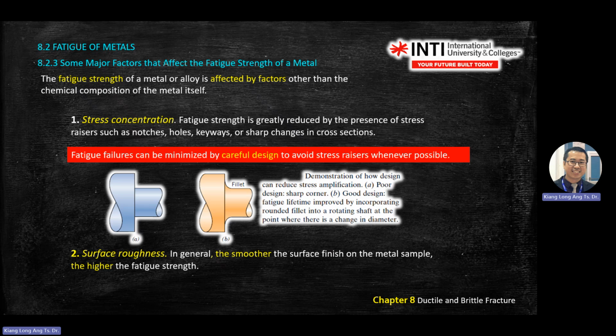Surface roughness also. Why surface roughness? Because surface roughness is actually how smooth your surface is. If your surface is not smooth, there are sharp edges like a saw. If you look under a microscope, it will be like this. So all these sharp edges are stress concentrators at the tip here. So this one will form A. This will be your A. So that is like what you calculate for KIC, all these things. Okay.